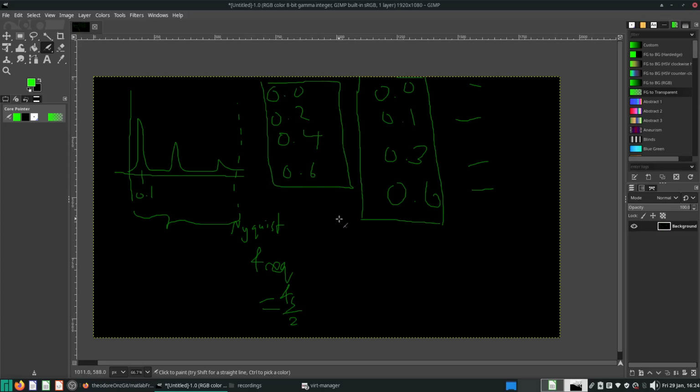If you have an evenly sampled data set, so you sample at normal intervals, normally your sampling frequency here, let's say, will be 1 over 0.2. And the sampling frequency then will be, I think, 5 Hertz.